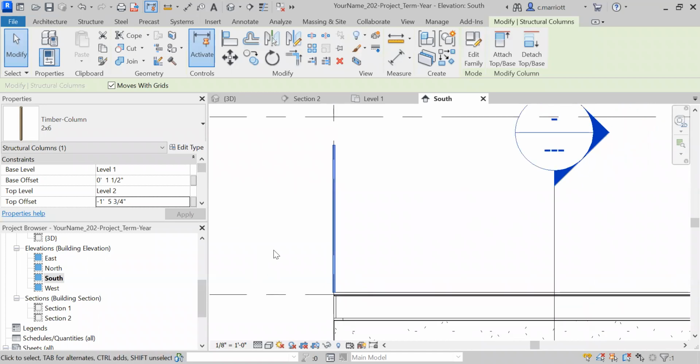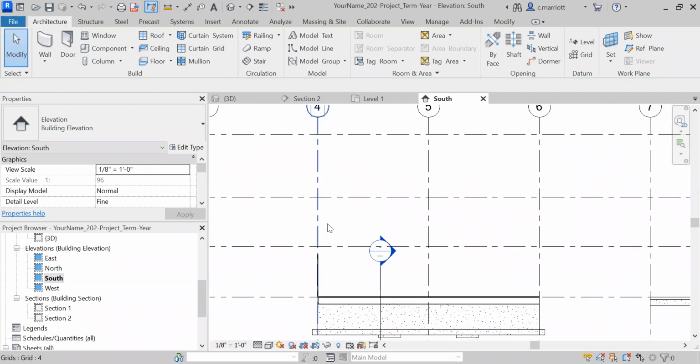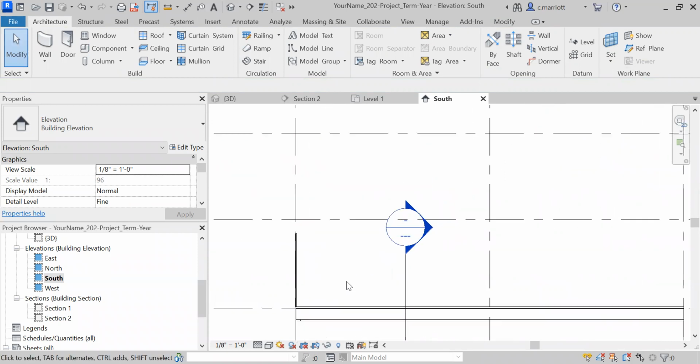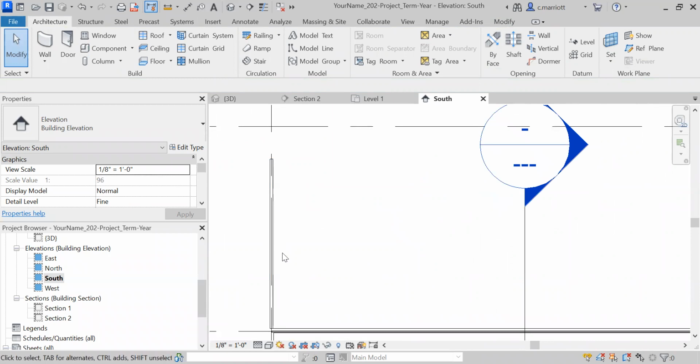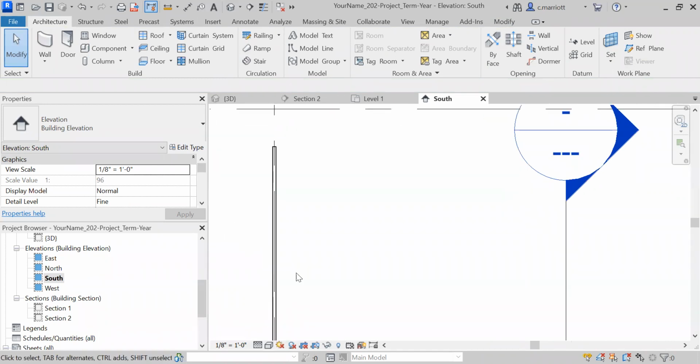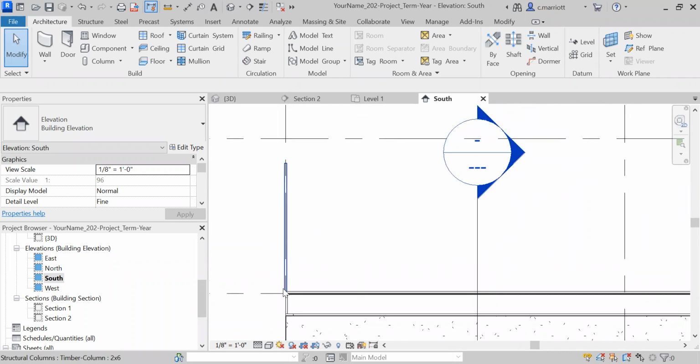Now this structure with these grid lines, these are 20 feet, each of them, which works out well for the modules of plywood. The plywood will be applied to the face of these exterior walls. And so the module on 4 feet centers means that you need to have a stud at every 4 feet. So the only one that will not be 4 feet on center is this last one.